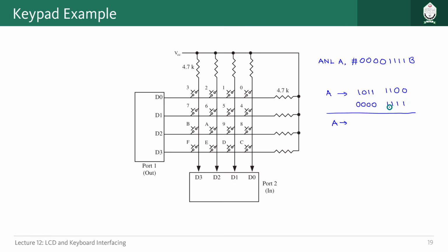That means for these 4 bits, whatever value we have will go through here, because 1 and 1 should be equal to 1, and if either of the bits are 0, then for that bit the result should be 0. That's the idea. So because all of the bits here are 0, whatever comes here will just become 0.